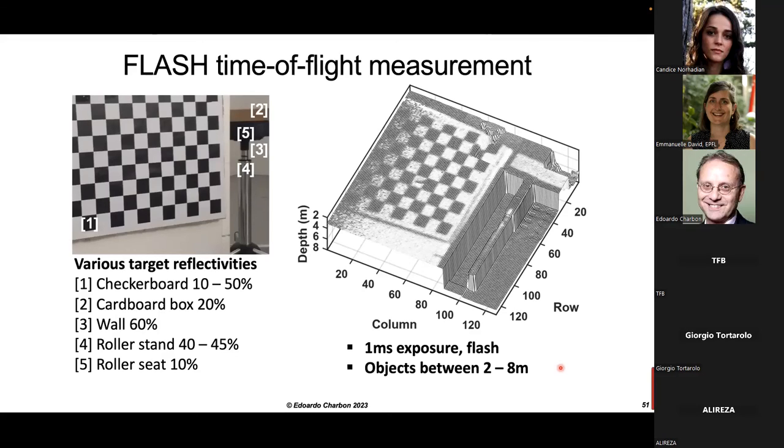If more than one is detected, it opens a window of 500 picoseconds and assumes that the light comes from the laser. The first photon and all the other photons following are converted through the same TDC into codes that represent the time of arrival of the photons. If just one photon is detected, it is assumed to belong to background and is discarded.